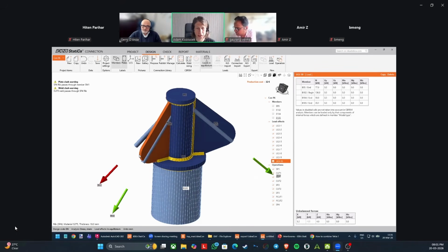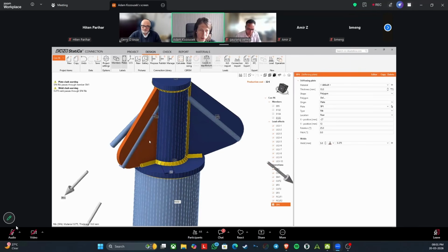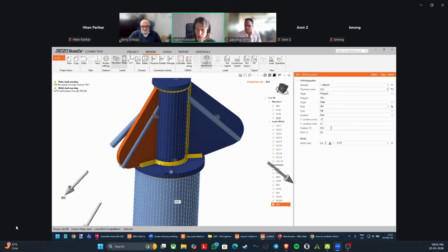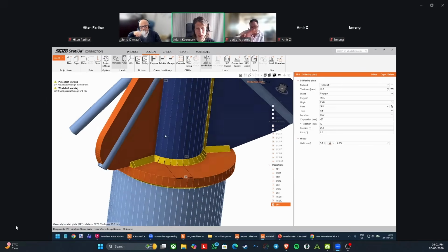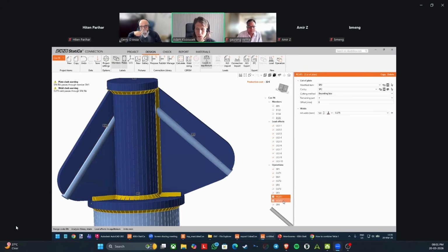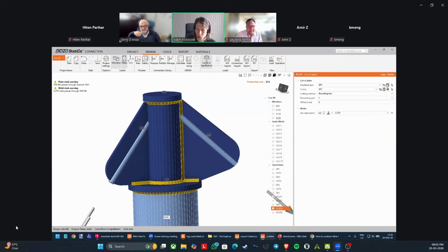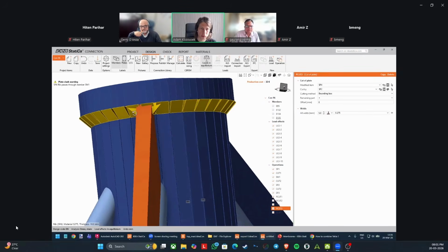All right, so that was a little bit of side information, and I will continue with constructing this detail. The last thing I did was position this plate. It's already welded, as you can see, on both sides. What I will do now is make this cut here and here. As I showed, I can multi-select, copy these two operations, and then change this plate and the SP2, so the cut is in place.